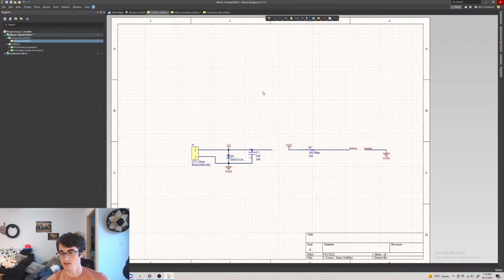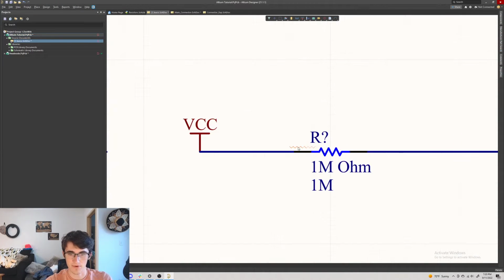Sometimes if you make changes, you want to explain to people, be like, hey, this might look really weird, but there's a reason why we're including it, because like the car won't turn on without it. But yeah, so that's kind of it with the schematic stuff. I think with the schematics, it'll get the most complex whenever you start adding more pages. Most of the starter projects or things you work on will probably begin with like 1 or 2. But the key is making sure whenever you update it on any page, make sure that if you're going to reference signals across both pages, use net labels and use power ports to reference it, and pay attention to these little red squiggly lines to see if that isn't referencing properly.